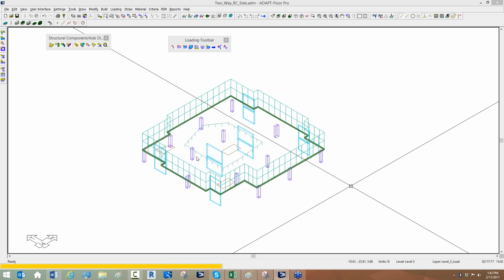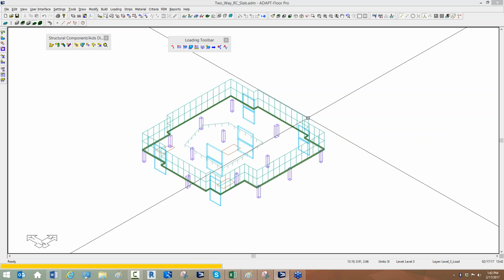Yeah, is there an easy way to do skip live load? And how about moving loads? Moving loads, I would say no, there's not currently an easy way to do that other than to use the skip patterns and move patterns around in certain locations. So you could create, for example, 10 unique skip regions and then define loading to those regions and then turn those regions off and on in load combinations. So that's really a very customized way to approach moving loads, Aaron, that I can show you.